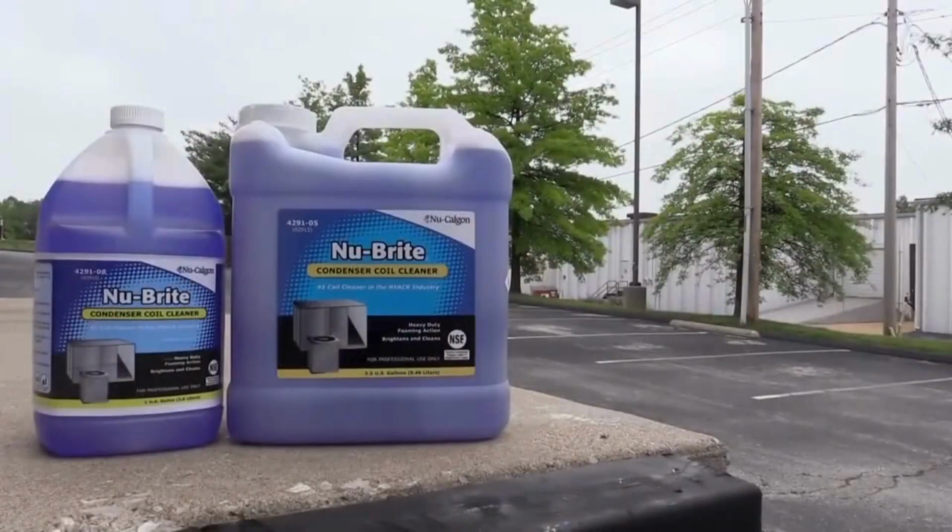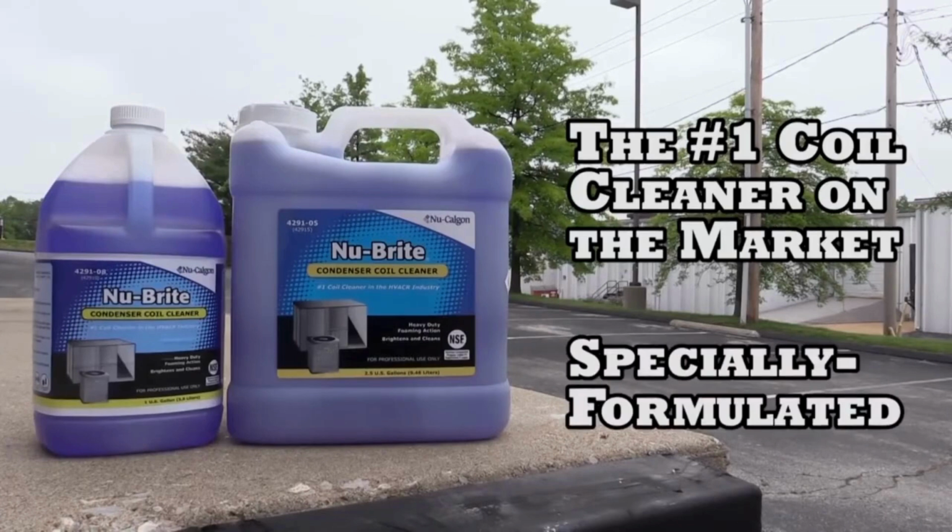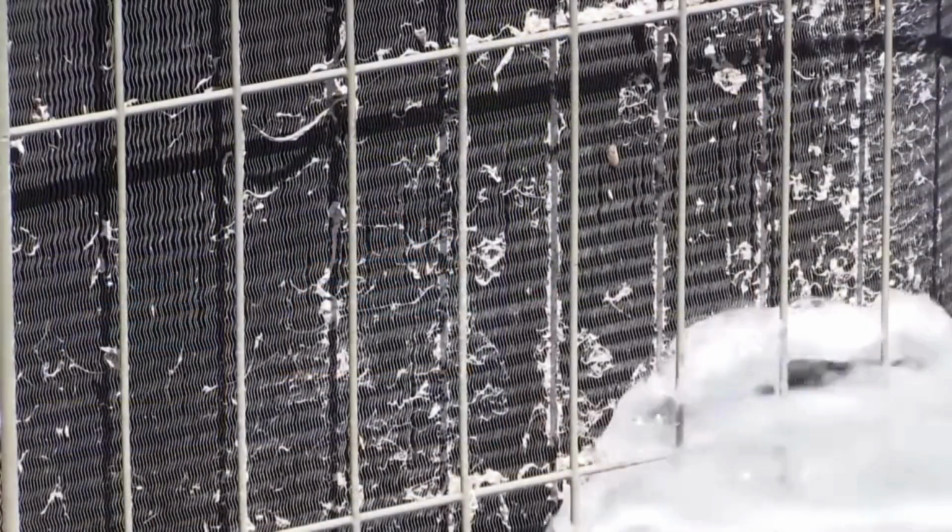Outdoor coils are exposed to conditions which allow dirt and debris to get caught in the fins of the coil. Water alone will not remove this dirt and debris, so it is important for you to use a coil cleaner like New Bright, the #1 coil cleaner on the market. New Bright is specially formulated with additives to produce heavy, stable foam, emulsifying grime in its foaming action. Additionally, these additives lift and hold debris away from surfaces to prevent it from redepositing on the coil before rinsing.